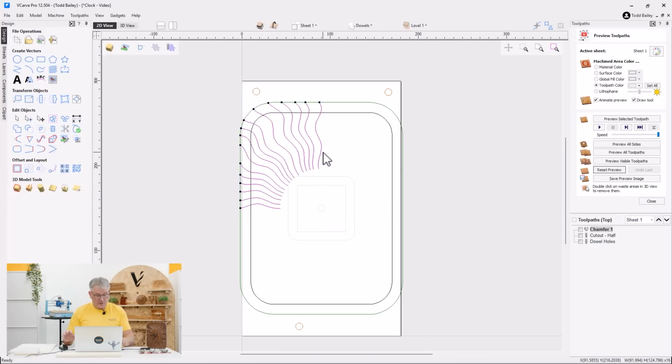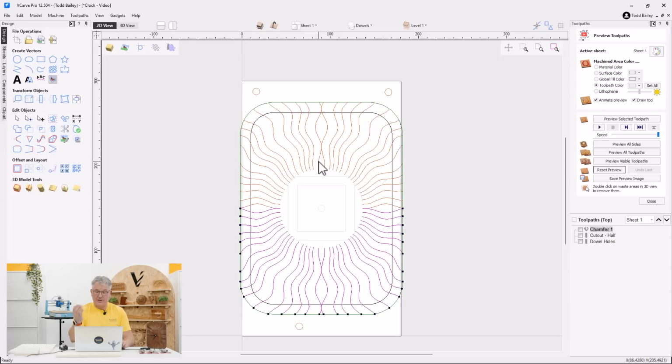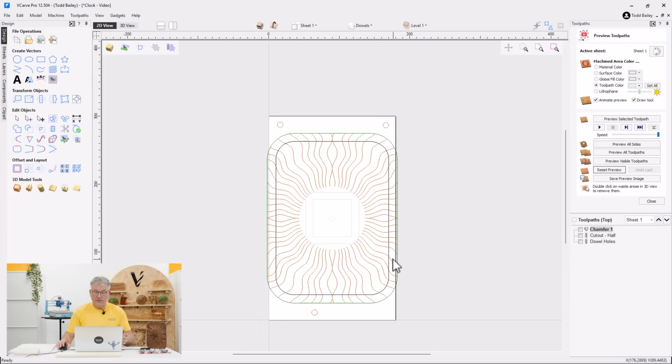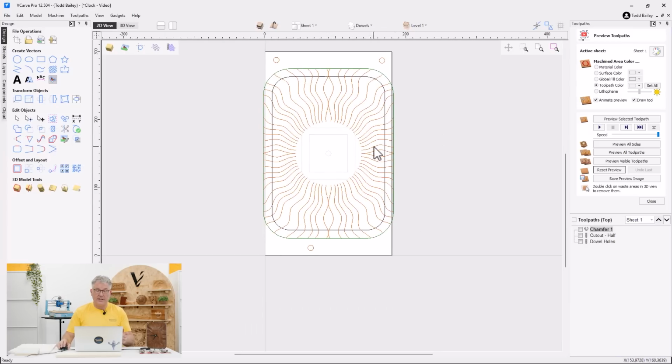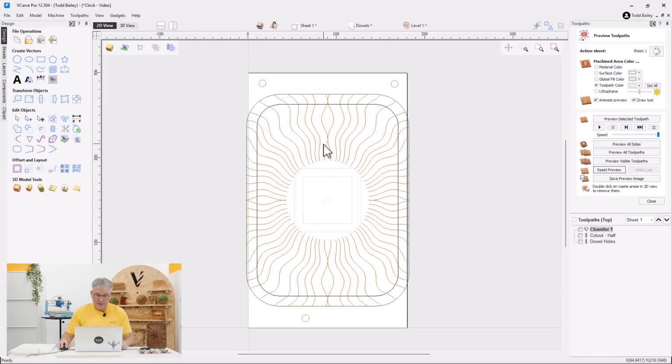And then I'm going to hold down my Control, Shift, and H key. That's going to copy those horizontally across my job. Hold down my Shift key again and grab those two. Control, Shift, and V, and that's going to copy them down. Now I have all the vectors that I need to go ahead and add a texture to the top of this. So let's grab those four groups.